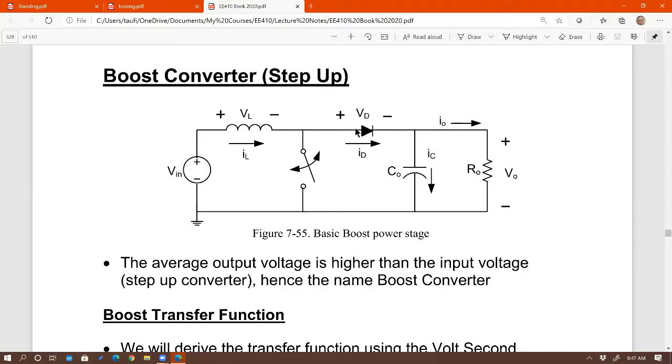And then on the output side, you have a diode that would be turning on and off, on and off, which means the current is going to be also on and off, right? So it's going to be discontinuous. So bad output current characteristics, meaning you're going to have to put heavier filtering at the output compared to the input.